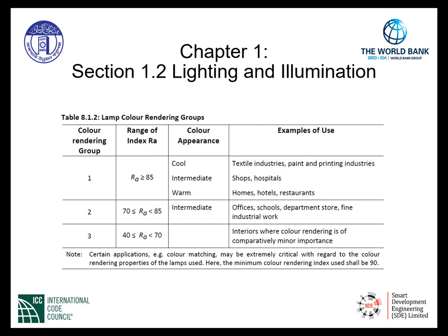The color rendering index defines the ability of a light source, which is a lamp in this case, to identify colors. It is measured on a scale of 1 to 100. 100 is natural sunlight, and 1 is light of a single color, monochromatic. With a higher rendering index, colors will appear much clearer and more vibrant. The next two columns provide the color appearance, where lamps of the various color rendering index should be utilized. Halogen and incandescent bulbs have an index of around 100, while LEDs are around 80, depending on temperature of the bulb.